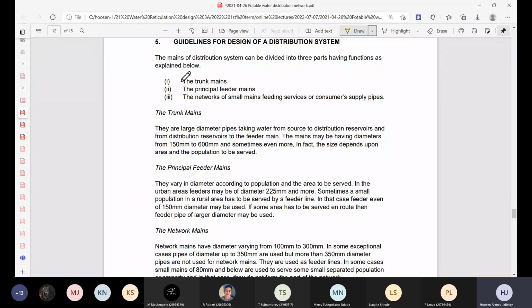We've spoken about these in the diagram: we generally break it down into three different kinds of pipes. We have the mains, the trunk mains, so that's the main supply pipe to the area. We then tee off from that, and then we have the feeder or the sub mains. And then we have our branches or laterals that go out and supply the consumers, your water consumers.